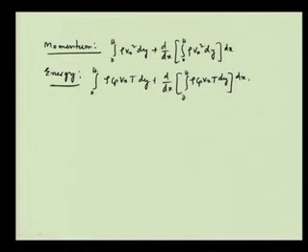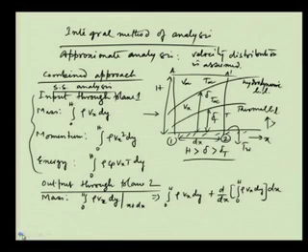Now, in addition to this, as we have discussed previously, momentum is transported from the upper direction to the lower direction, and heat is transported, in case of heating, from the lower to the higher direction. The fluid above the boundary layer has much higher momentum because it is moving with a velocity v infinity. As we go ahead, any higher layer of fluid will have higher momentum than the layer below it.